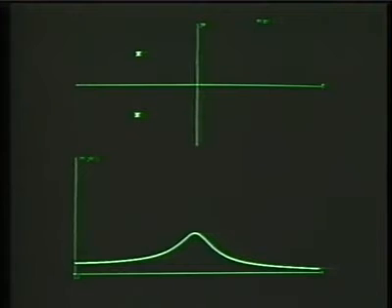Next, we'd like to look at the behavior as the poles move parallel to the real axis, first closer to the j omega axis and then further away. As they move closer to the j omega axis, the resonance sharpens because of the fact that the pole vector gets shorter and responds or changes in length more quickly as we move past it, moving along the j omega axis.